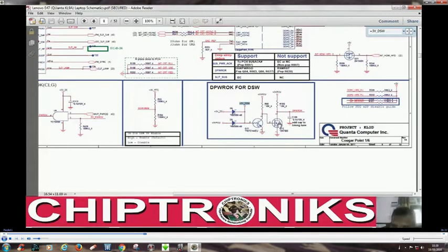This is an N-channel MOSFET. You see the arrow is inside. For an N-channel MOSFET, it will be activated when VGS is greater than 0, that is, the voltage at the gate should be greater than the voltage at the source. But here the voltage at the gate is 0 volt and the voltage at the source is 0 volt, so this MOSFET is turned off.